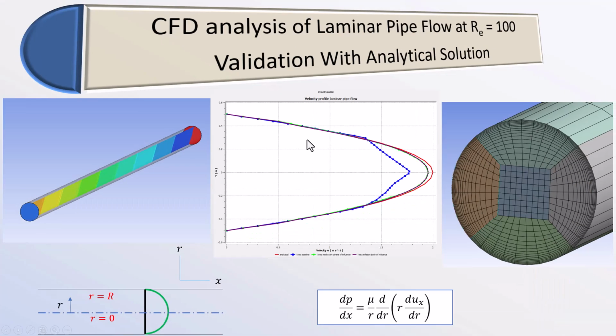The reason hexa meshing produces high quality results is because of two reasons. Number one, the mesh is aligned to the flow, we can control the mesh in the boundary layer, and the cell shape is hexahedron. Number two, tetra meshing has a tendency, especially a problem for internal flows, to grow the size from the surface sizes to the interior of the geometry. So we will have very few cells in the interior of the domain, and this is okay with external flows.